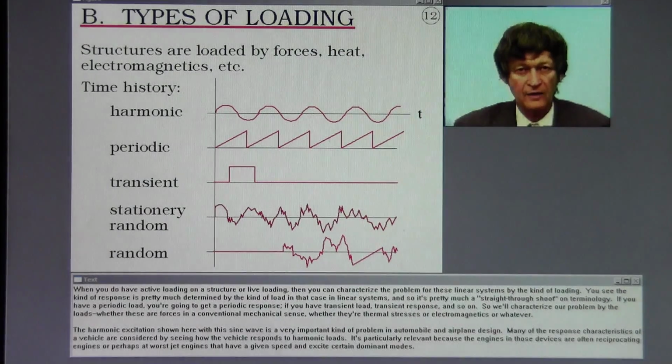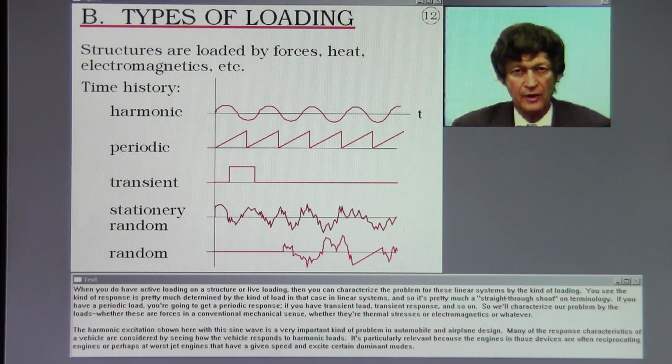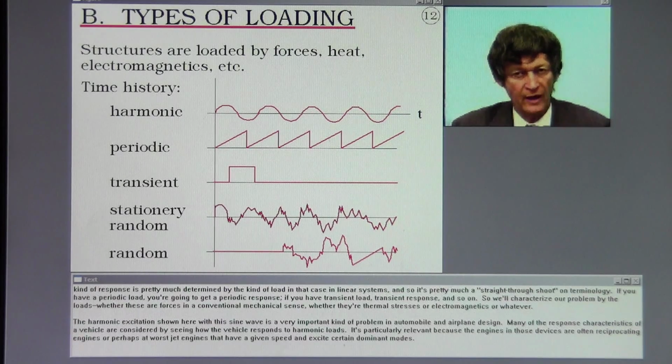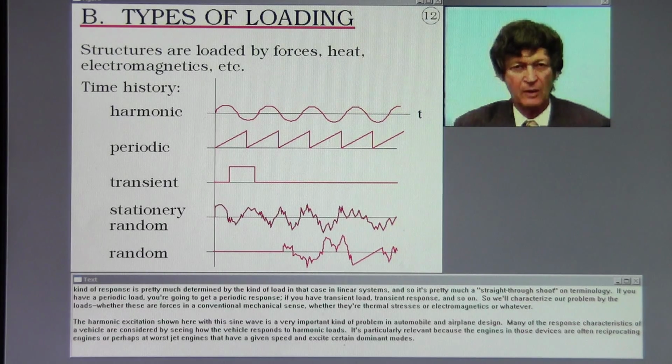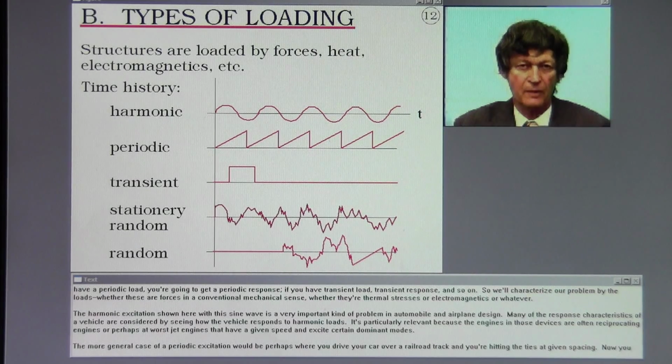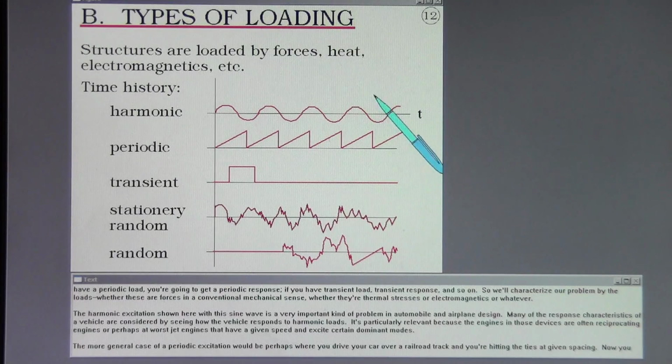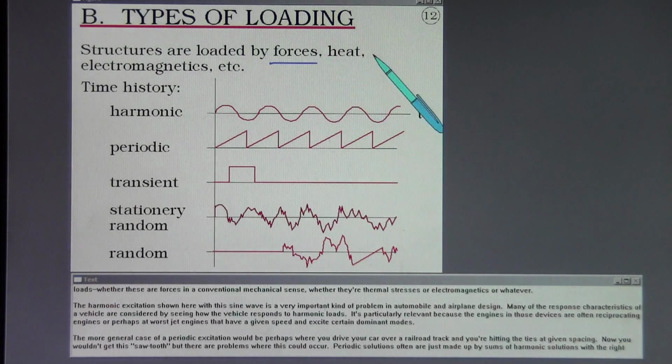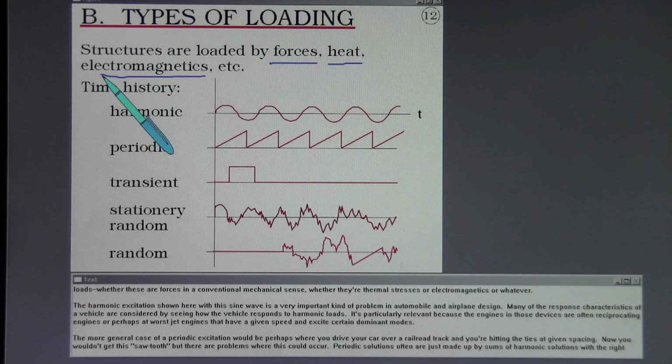When you do have active loading on a structure, or live loading, then you can characterize the problem for these linear systems by the kind of loading. You see, the kind of response is pretty much determined by the kind of load in that case in linear systems, and so it's pretty much a straight shoot on terminology. If you have a periodic load, you're going to get a periodic response. If you have transient load, transient response, and so on. So we'll characterize our problem by the loads, whether these are forces in the conventional mechanical sense, whether they're thermal stresses or electromagnetics or whatever.